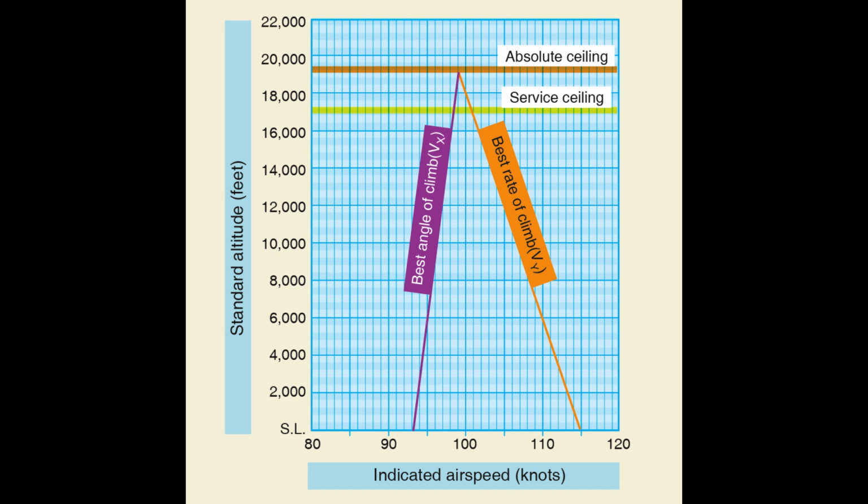As the center of propeller thrust moves to the right, a left-turning yawing moment moves the nose of the airplane to the left. This is compensated by the pilot through right rudder pressure. In addition, torque that acts opposite to the direction of propeller rotation causes the airplane to roll to the left. Under these conditions, torque and P-factor cause the airplane to roll and yaw to the left. To counteract this, right rudder and aileron flight control pressures should be used. During the initial practice of climbs, this may initially seem awkward. However, after some experience, the correction for propeller effects becomes instinctive.